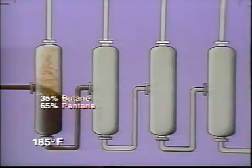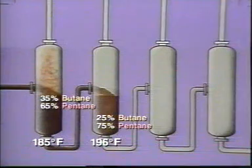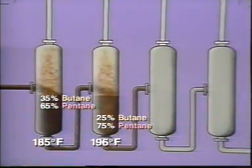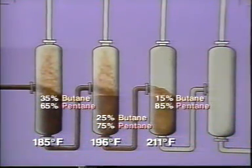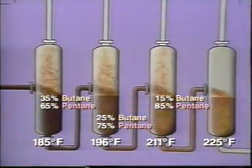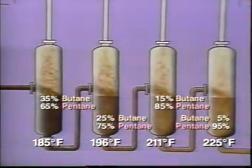If we place this mixture in a second still and heat it to, say, 196 degrees Fahrenheit, even more of the butane will boil off than did at 185. This changes the composition of the liquid to 75% pentane and only 25% butane. By passing this mixture through additional stills that operate at higher and higher temperatures, we can eventually form a pure pentane fraction.